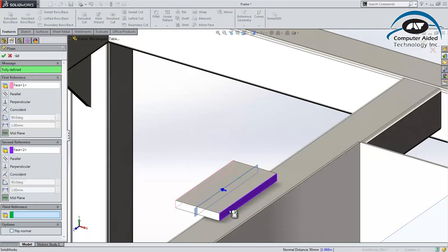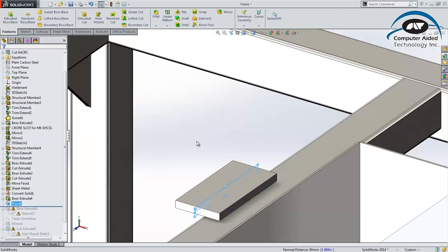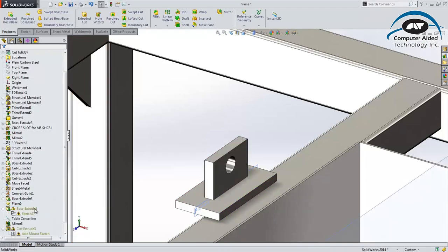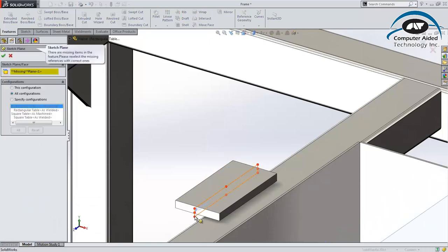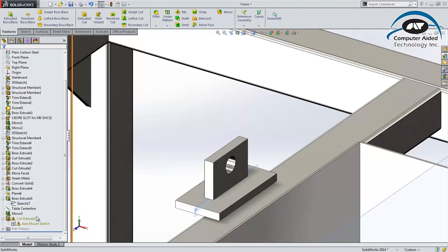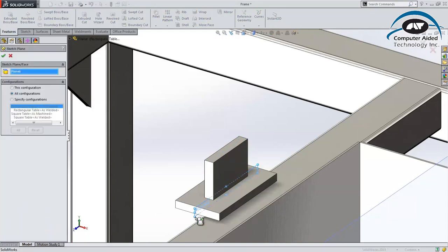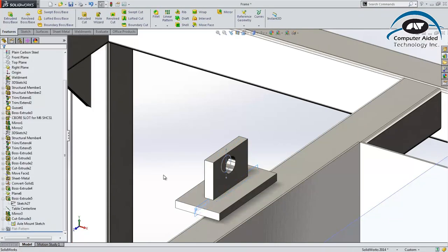When you create reference planes in SolidWorks, you can now control the direction of the normal condition, giving you more control and ensuring that any downstream changes affected by it are in the proper position and orientation. Now, to redefine the missing references we removed previously is as easy as selecting the new plane. And because we set the normal direction, nothing has changed or presented a warning.